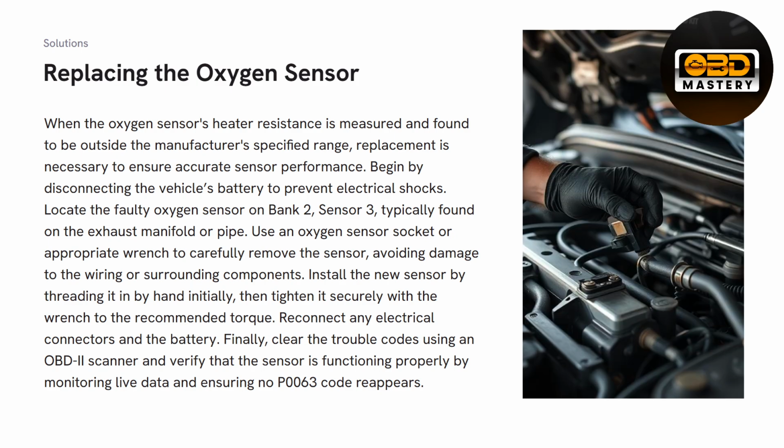So moving on, replacing the oxygen sensor, super easy, but you're going to want to make sure that you look for it. It really depends on which car you have, so I can't really recommend a specific area where it's going to be. However, look at the oxygen sensor, make sure that you are replacing it with the right tools and much more, and reconnect any electrical connectors in the battery, and clear any trouble codes once you're done. You can have a read at this if you want by pausing the video. However, we're going to move on here.